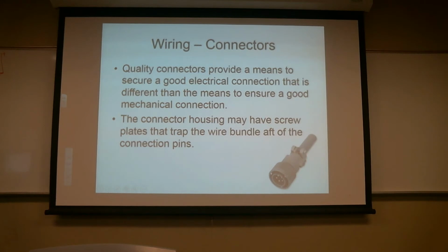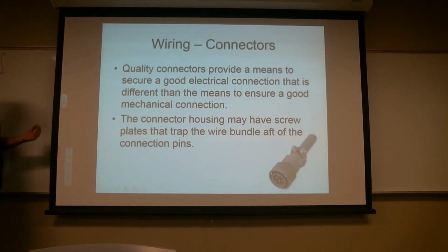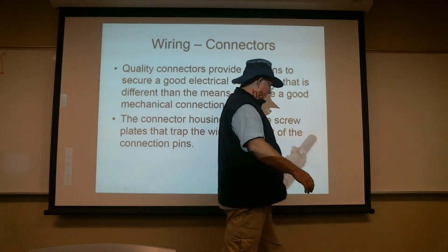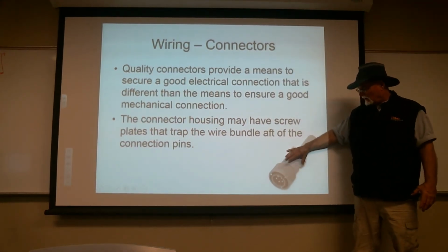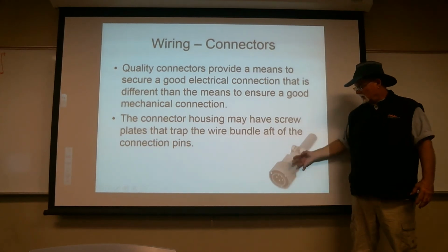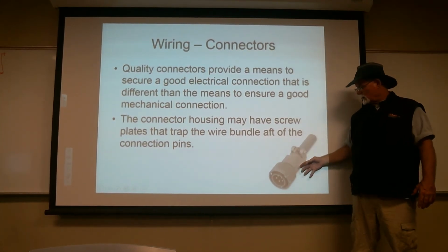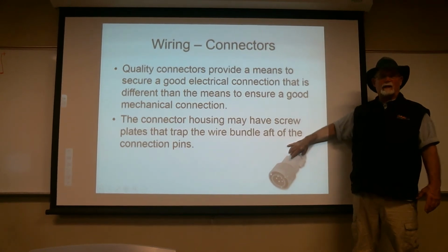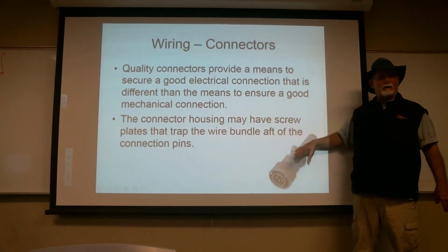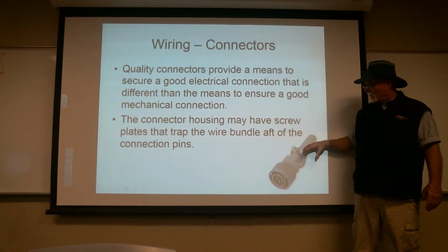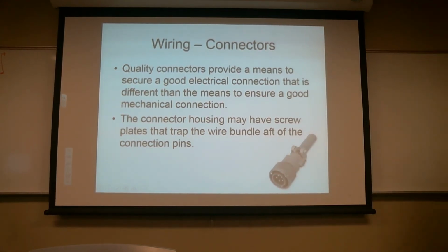So typically, we often will separate the mechanical connection from the electrical connection. A very common plan form is they create sort of a housing shell with the connector end, the inner shell that holds all the pins, and then out towards the back they have a set of clamp plates. The clamp plates could actually be internal to the shell, but they are designed to grab around the entire bundle of wires and squeeze against them, not cuttingly, but it's better to pinch that whole bundle of wire rather than hanging on to one little bitty wire out here.